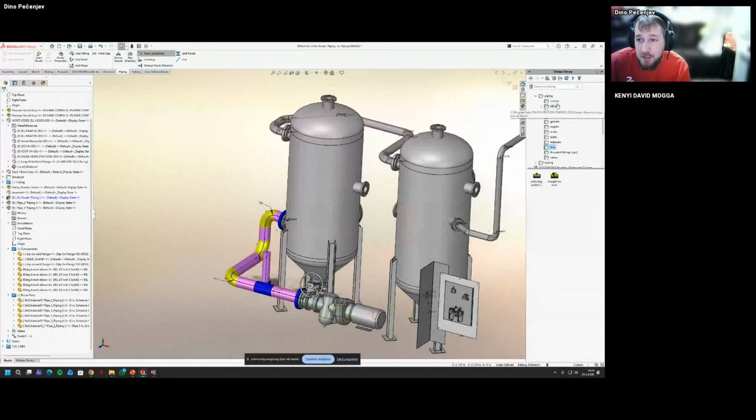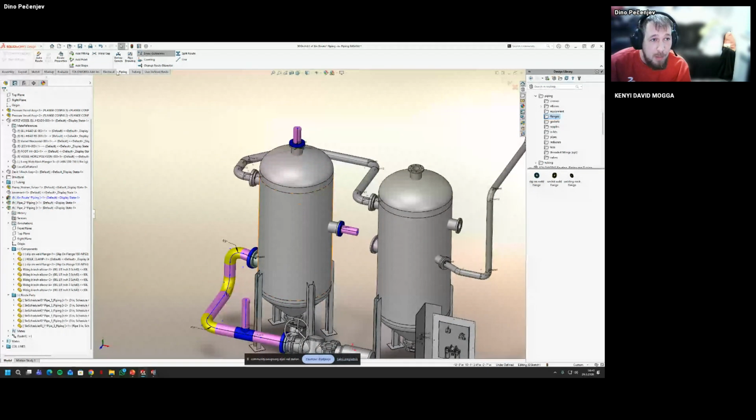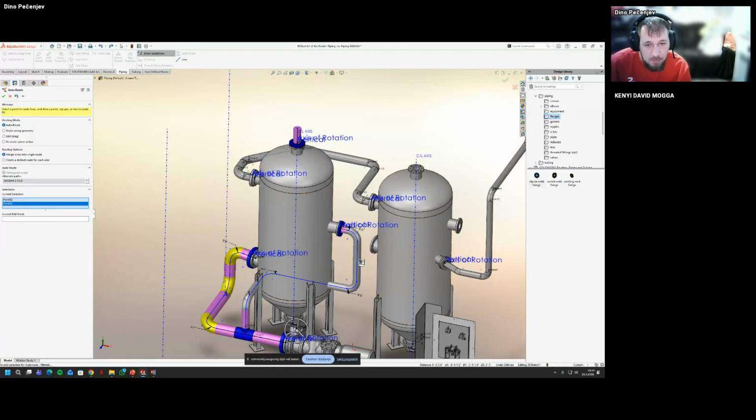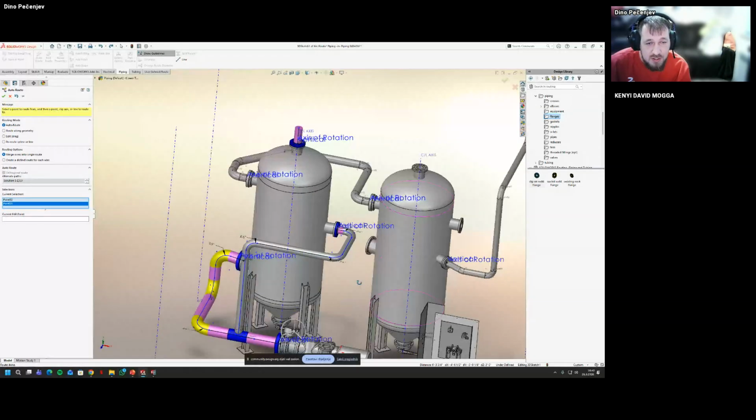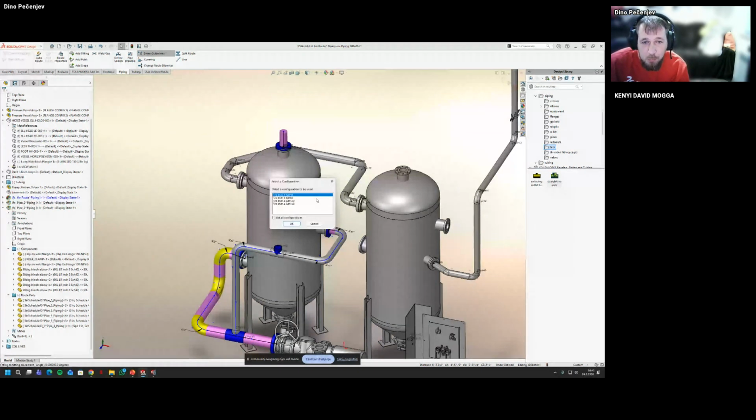And here, let's say we're going to add 2 more flanges. So just drag and drop. We're going to use this, and place one here. I'm just going to use the auto route because this is a simple part, and I'm going to use this solution. And let's say I want to continue this part to here. For this example, I'm going to use a straight T and just put it upwards.